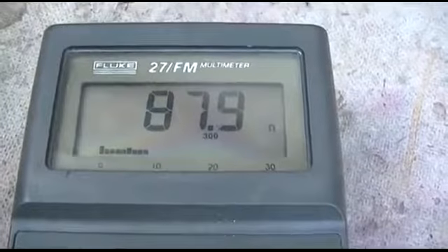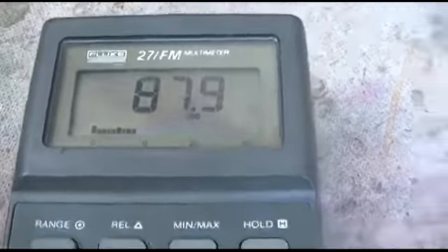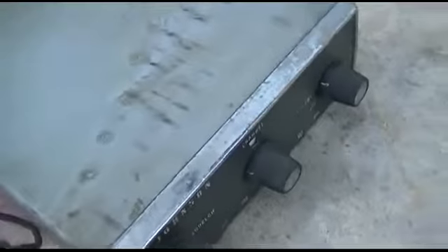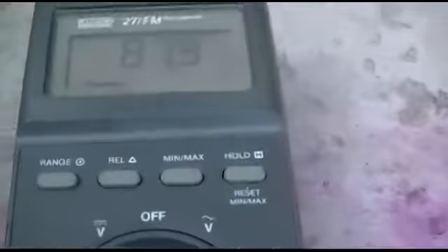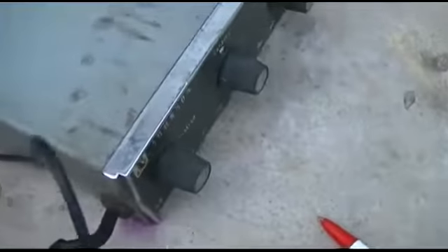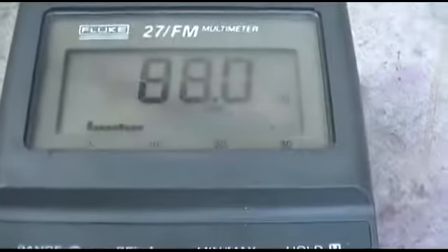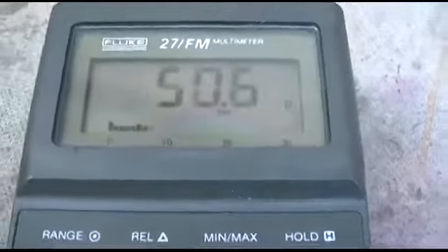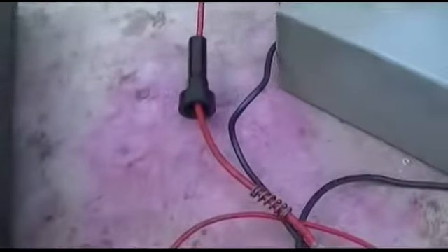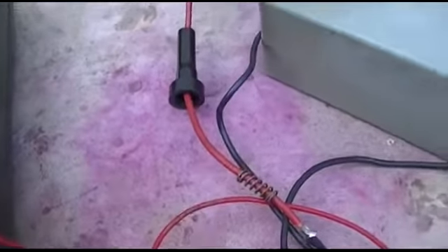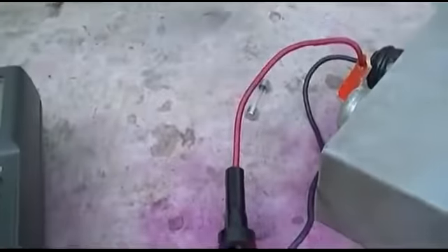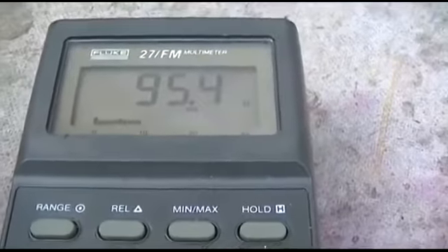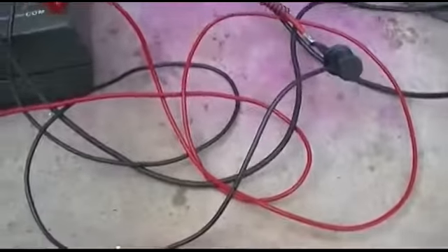That doesn't seem that excessive, especially since it has dial light bulbs in it, where the resistance goes way down when the filament's cold. So if we turn it off, okay, but yet it's blowing a 5 amp fuse, so this does not mathematically calculate right now.